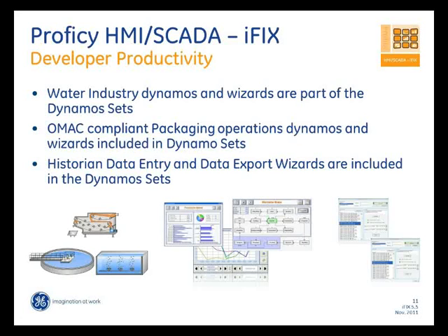The other two capabilities that we also added in iFIX 5.5 were what we call the historian data entry wizard and a data export wizard. So with historian data entry, you can actually do manual data entry directly into historian using a timestamp and a value. So any lab data that you want to enter or any manual data that an operator might have collected across his plant, he can at his leisure go in, enter the value using the timestamp of the value recorded, and it goes right into historian at the timestamp that the operator or the supervisor might have specified.